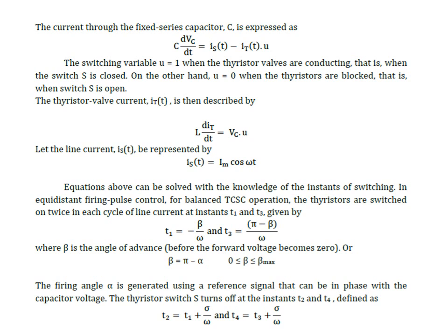That is nothing but, if you consider three phase converters, we have three branches and six thyristors: T1, T2, T3, T4, T5, and T6. And how these thyristors are connected in a single branch, and how the thyristors are switched. In case of three phase, in forward mode, two pairs of thyristors will be in positive direction or forward mode. Then, in order to switch the next mode, we have some conduction of the previous pairs of thyristors.